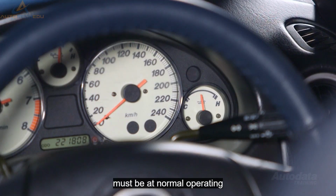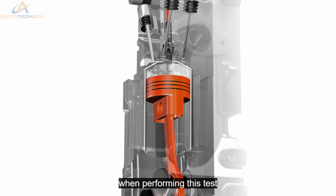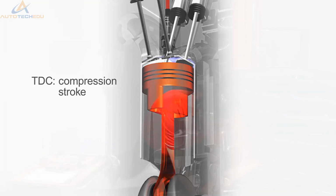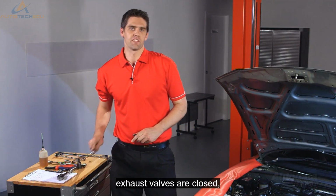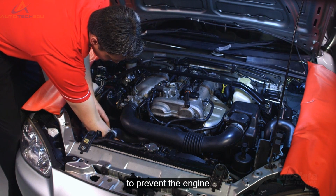Again, the engine must be at normal operating temperature. Remove the spark plug on the suspect cylinder. When performing this test, it's critical to set the affected cylinder's piston to top dead centre on its compression stroke. This ensures both intake and exhaust valves are closed. Secure the crankshaft to prevent the engine from rotating.